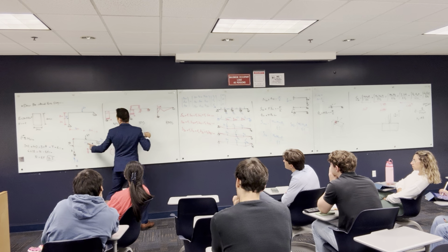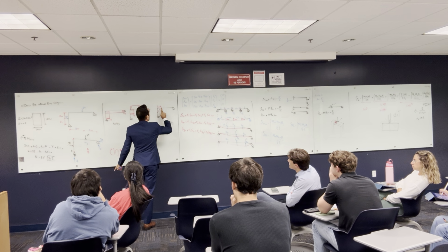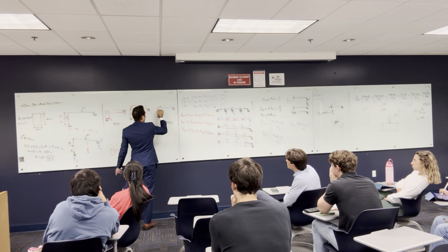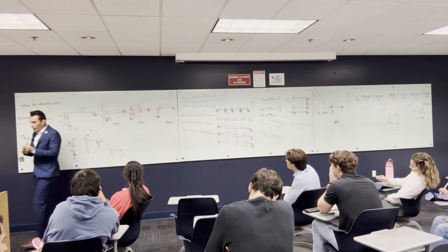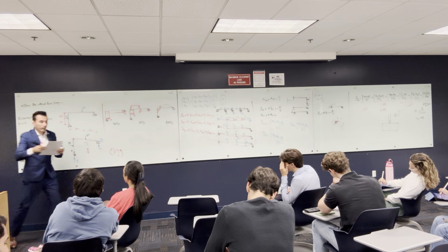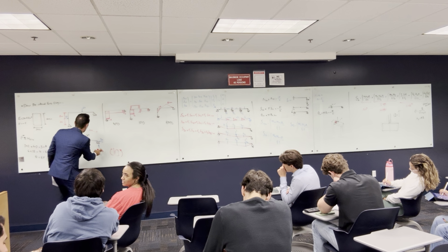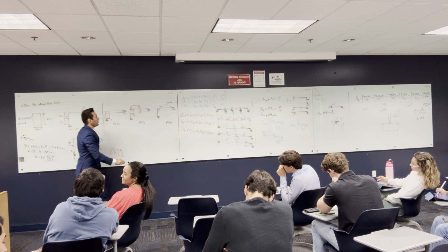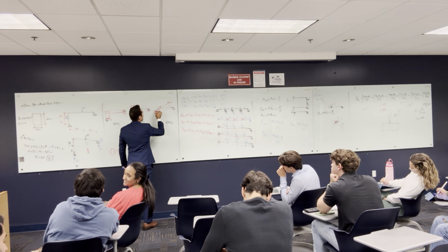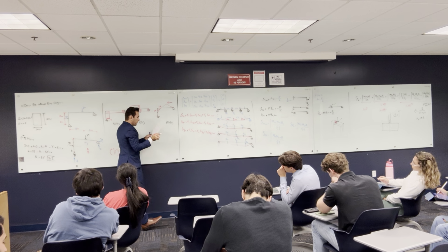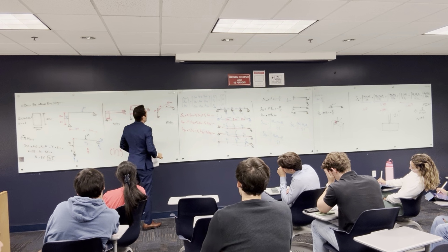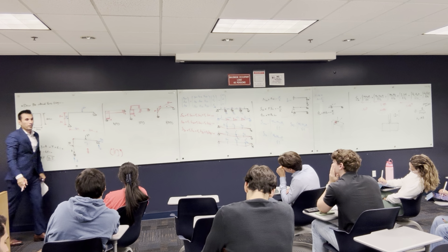something like that. But let's be consistent and make the positive up and the negative inside, so this is going to be something like this. Check. Yeah. The value here is going to be 6 Nm, because 2 multiplied by 3 gives you 6 Nm, and the value here is going to be 6 Nm to counter this value. So this is positive, and that's the bending moment. Did you guys get it?